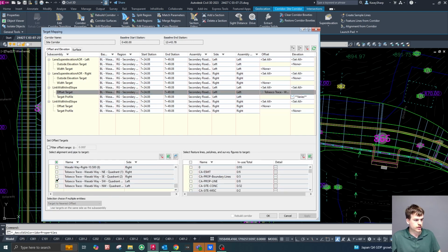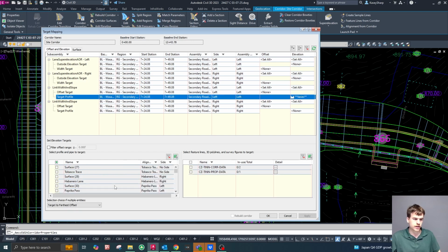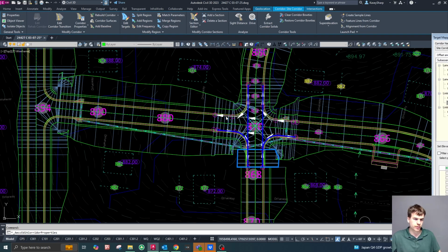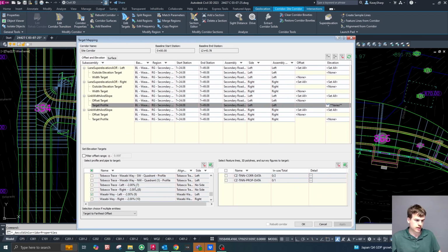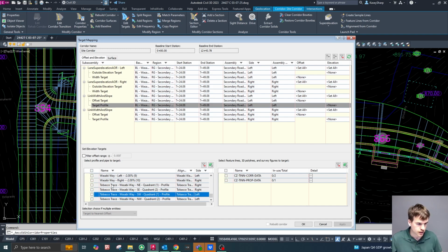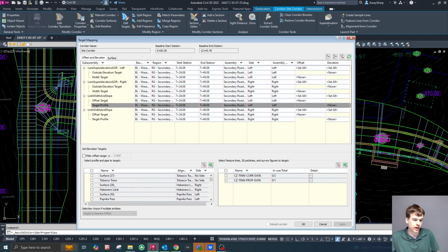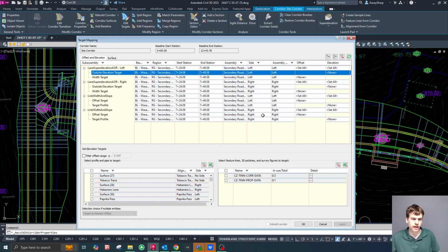And the more intersections you create, the more of these alignments it's going to generate. As you can see for the intersection, if I move this over here, it generates a bunch of these alignments. It's all these white lines with the arrows here. So this box is just going to get more and more crowded. So working with intersections can be very tedious, but it will do a lot of grading for you, which is really helpful. And once you get the hang of it, it'll make everything a little bit quicker.